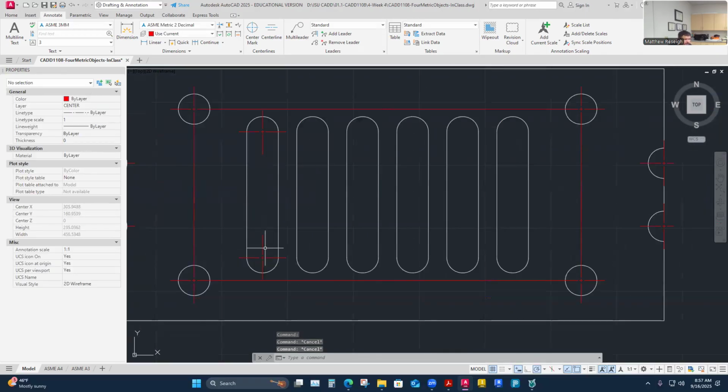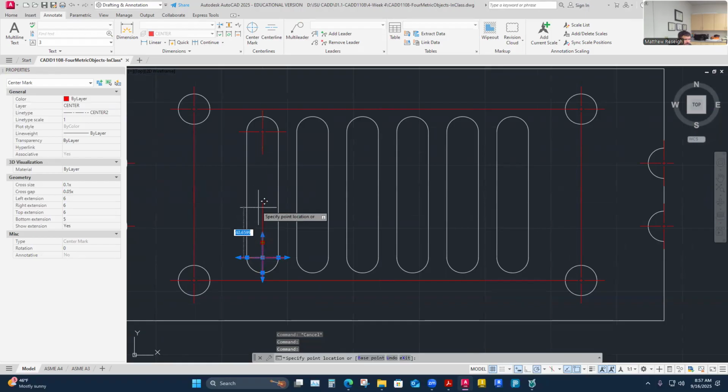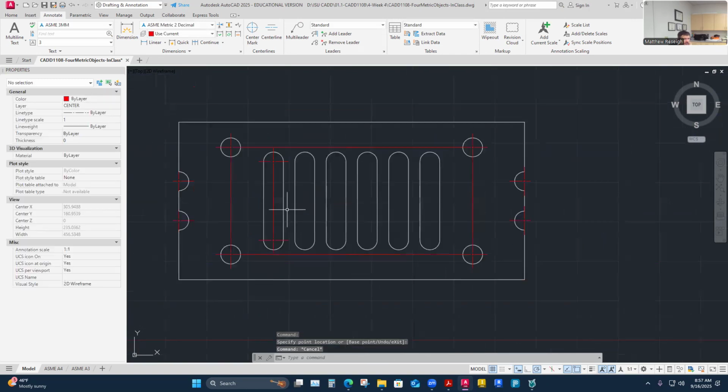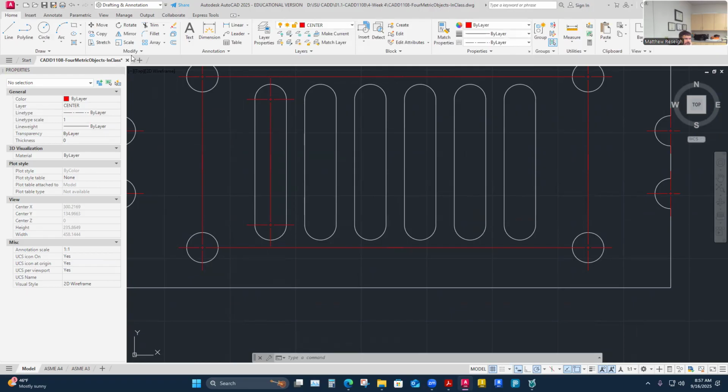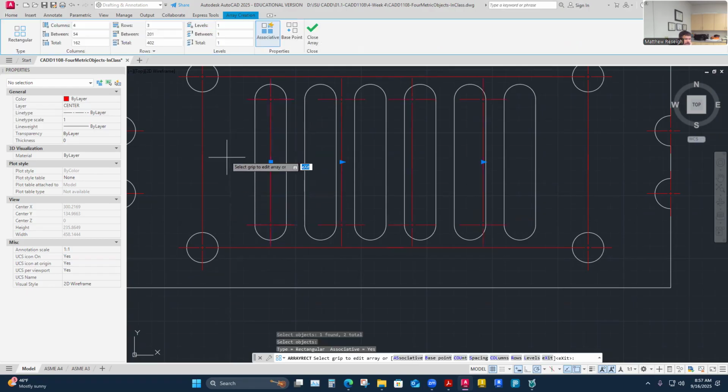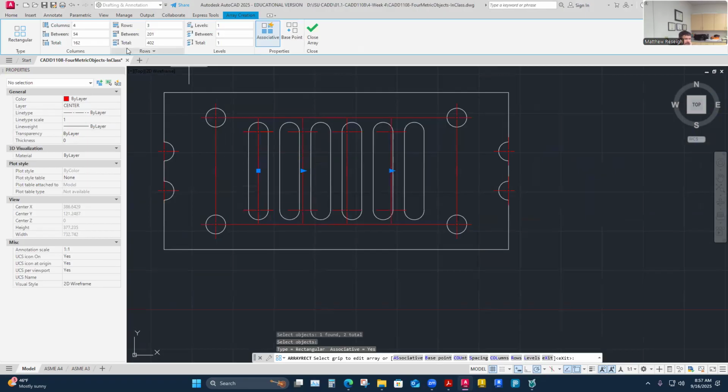And then I'll pull them together. This one here, I'm going to adjust the same way. I'll reference that, and then I'll do this one. So really, to me, that's like a finished slot center line, and I could array this. So I can just go to array. It's a rectangular array. We can use it again. It's going to be both of these objects because I'm going to array them as one. So I select both, enter, and then it wants to go into that array pattern that I need.